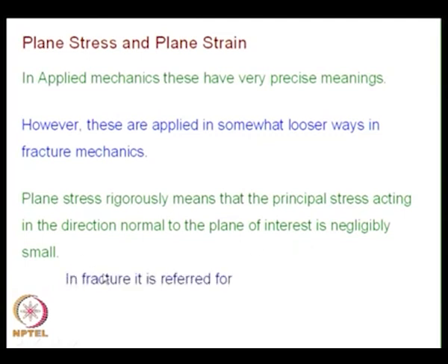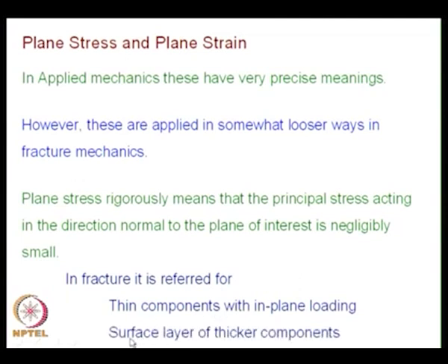In fracture, what do you call plane stress? It is referred for thin components with in-plane loading, and we also do one more thing. We say the surface layer of thicker components behave in a plane stress fashion. This is something unusual. This is so convenient for us to develop certain concepts in fracture mechanics. So, we have adopted a slight variation in the definition of what is plane stress and plane strain in the context of fracture mechanics. So, you have to recognize that there is a difference.